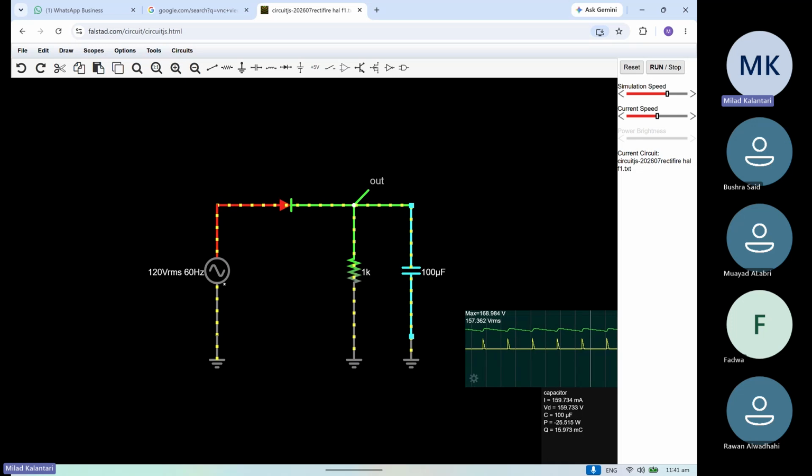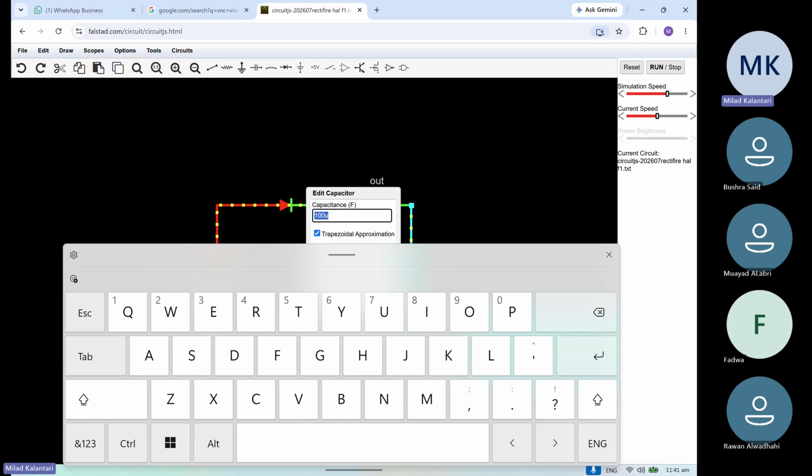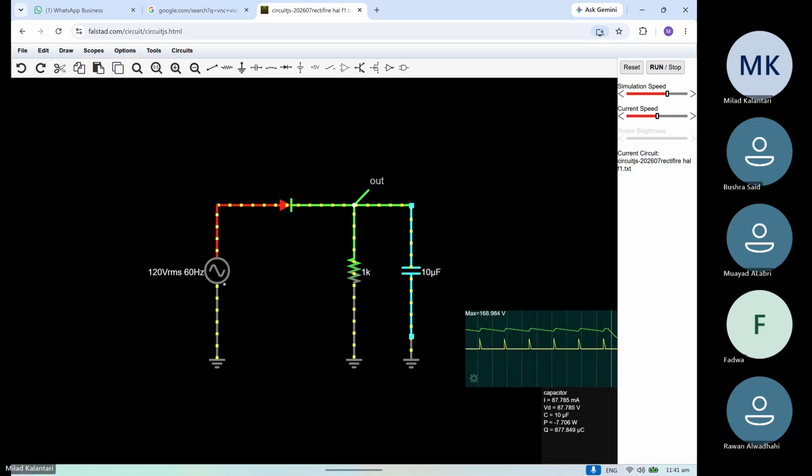The capacitor is charged. You have basically an RC circuit, right? The other side is just disconnected. In the RC circuit, what you expect is it starts discharging exponentially with some time constant, right? You know how to calculate it. The time constant of this RC would be what?